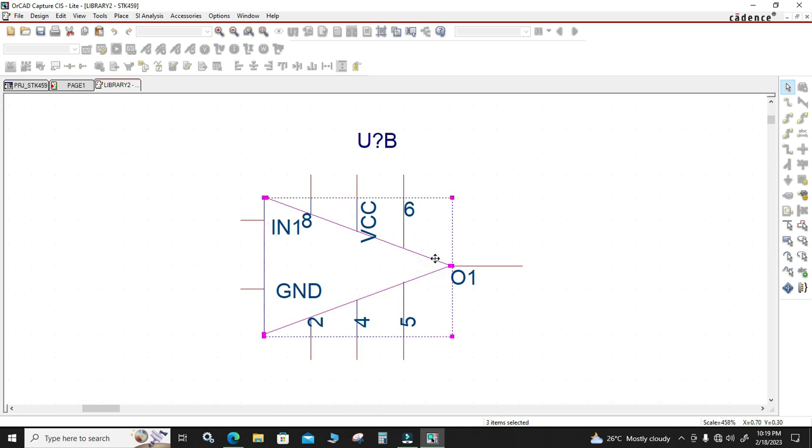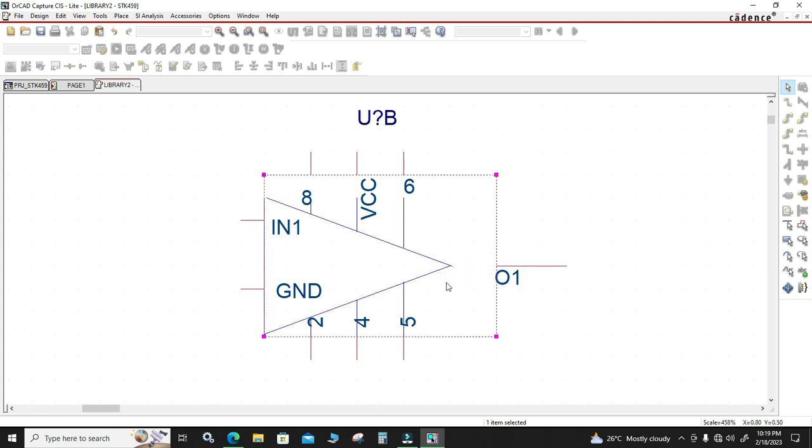First we need to rotate this symbol. Expand the outside, rotate is simple, graphic properties is open, graphic editing options are okay. How do we select these three lines?